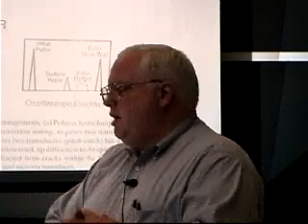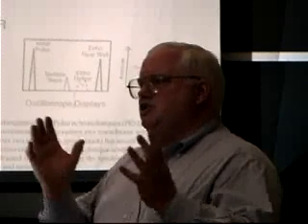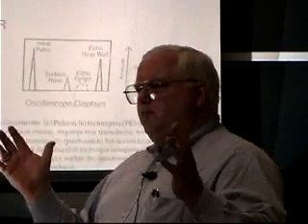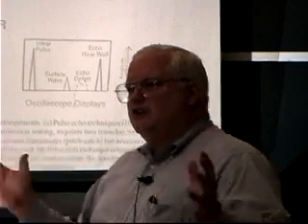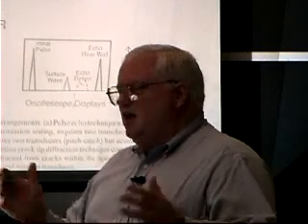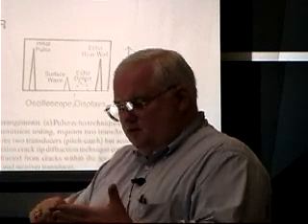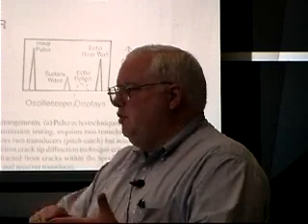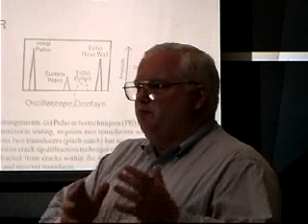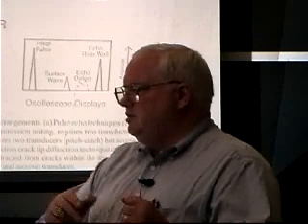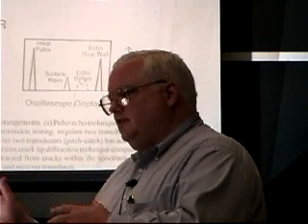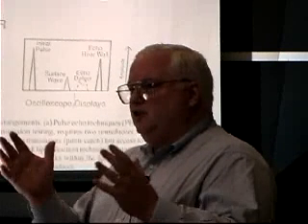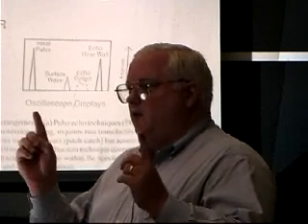So you pig the pipeline, and you get indications, and in 20 miles, you record lots of data. And you then have someone who doesn't have anything better to do, and they sit there and they look at wherever there's a little blip. And you compare the blips from the last time you did it 10 years ago to the blips you have today. And if you get a new blip, you say, ah, we have an indication.